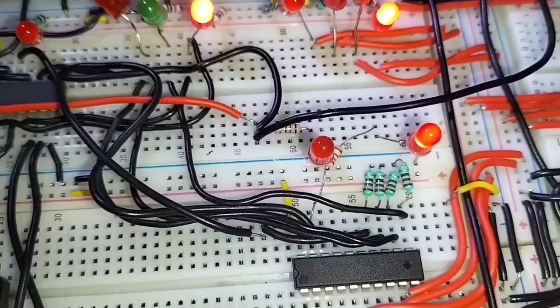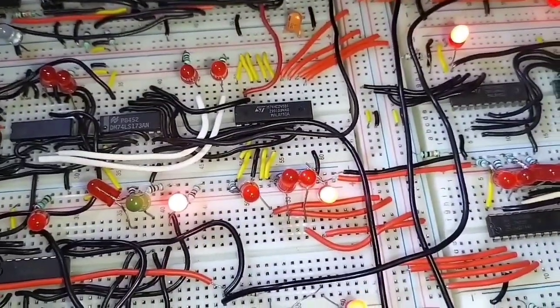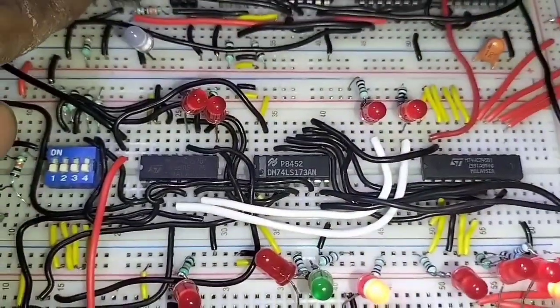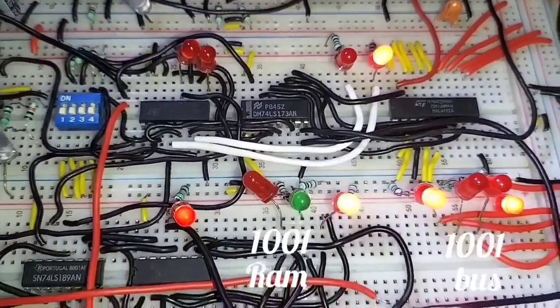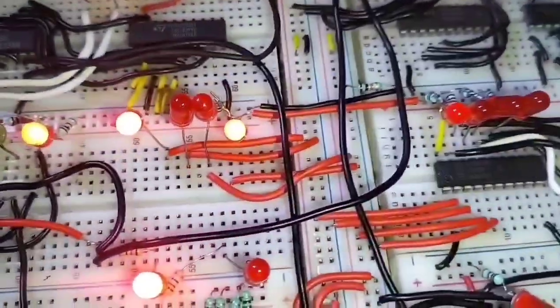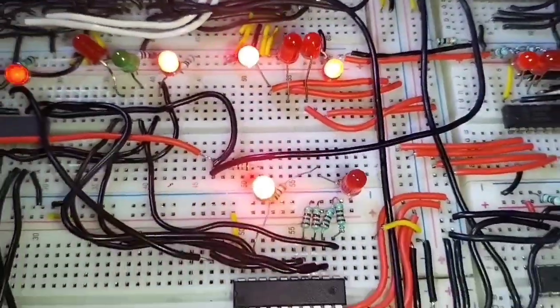for loading this data into the B register. For this we have to give one more clock pulse so that we can get that data on the bus. Here it is. Now RAM out, counter enable, and B register in micro instructions are active.